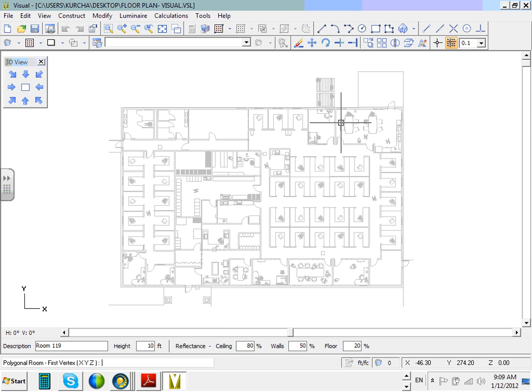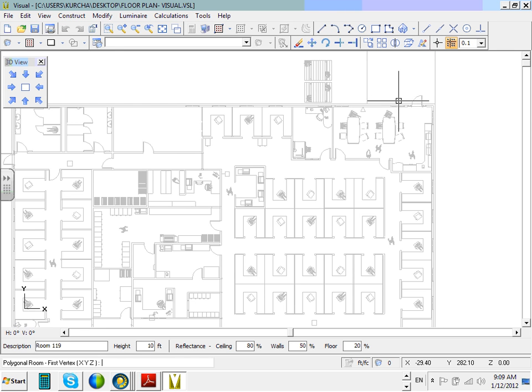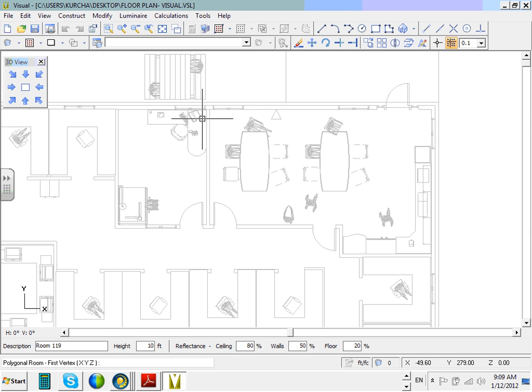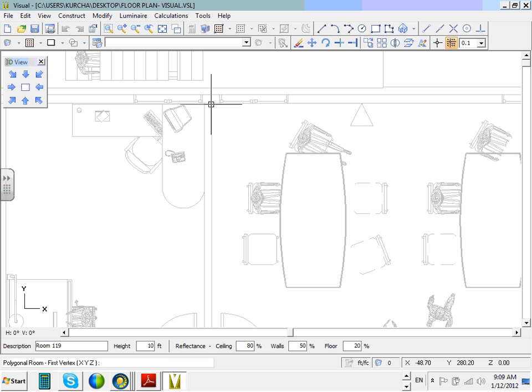Cool. Okay. Now I want to go construct the room. Start with one corner, zoom a little bit on one corner, and can you guys see now? My conductors are not ortho, so see where it says ortho here? Hit ortho, so it gives you ortho. Everybody picked ortho and the snap point 1.